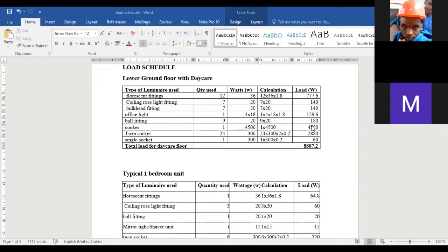so the extra 5 amperes, with time, it hits the cable because there is something called I squared R, that is heat. I squared R T. You must have learned this, whereby I is the current, R is the resistance of the cable, and T is time. With the time, the cable will heat, and that is the kuchomeka.